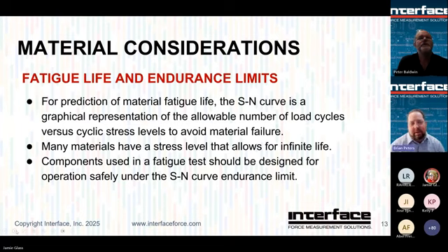Some materials certainly have a level that, if you stay below that threshold, will have an infinite life. Not all of them do, however. We're going to handle the load cell part, but for everything else in your load string or your test article, you need to be thinking about that SN curve. You don't want a premature failure well ahead of what you expected. Pretty basic design, but something that is maybe overlooked on other components, including fasteners.